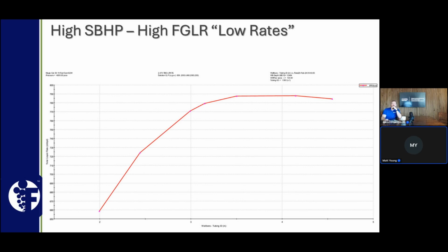So in a case like this, if we were presented with 7" casing, then we might pick 3.5" tubing as our flow path. If we had 5.5" casing, then we may consider either 2 7/8 or 2 3/8 annular flow inside that 5.5" casing. Because really anything larger than 2 3/8 inside 5.5 cross-sectional area would hinder production and not help us maximize that production. So something to note as we begin to manipulate our GLRs, our liquid rates, things like that.